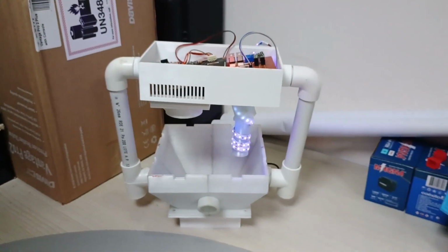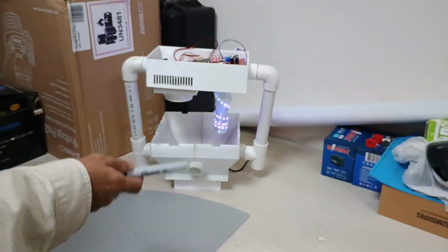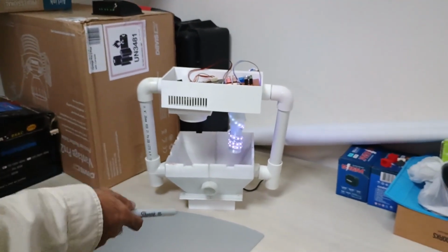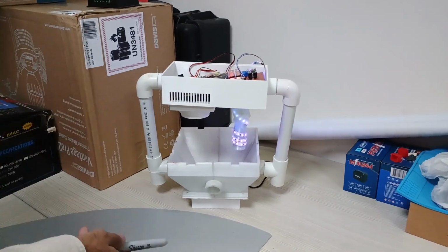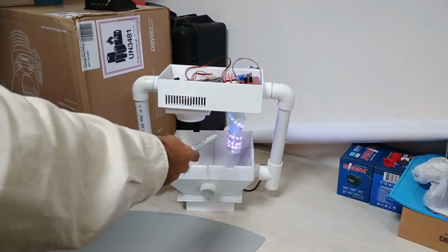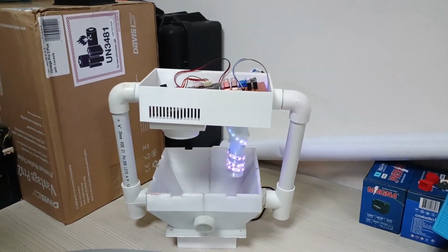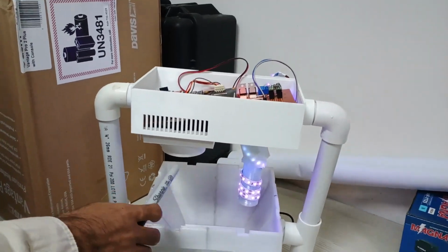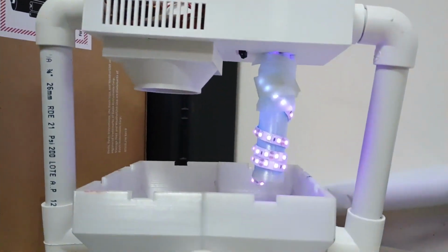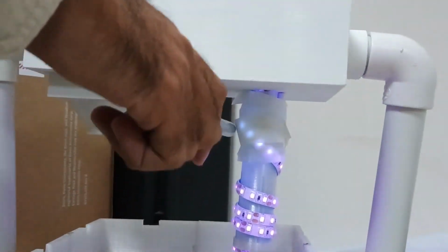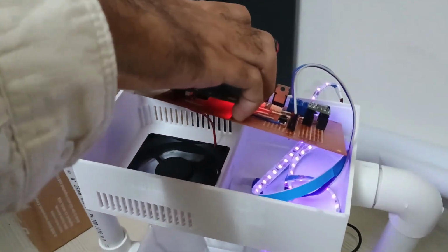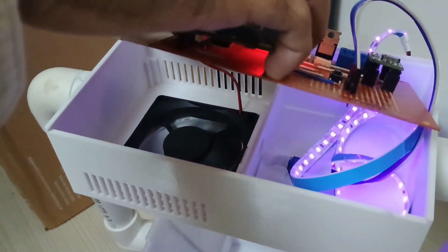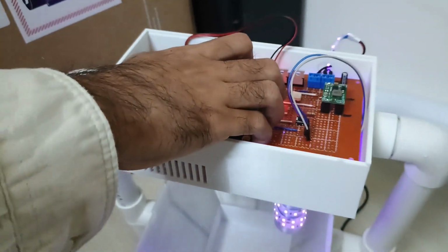Okay, so now we'll show you the demonstration of our automated light trap. The system operates as follows. At night hours, around 7 p.m., when the moths start to be active, the system turns on a UVA light automatically. Near the light source, there is a little IR sensor that generates electrical pulses every time a moth passes through. When a specific amount of pulses is reached, the fan turns on to capture the insect.